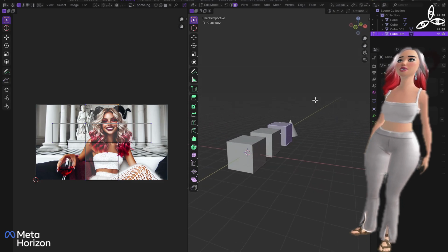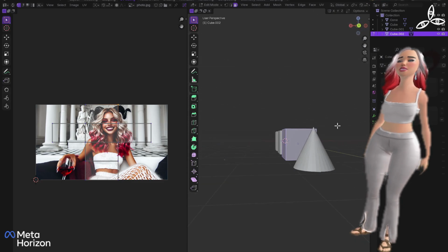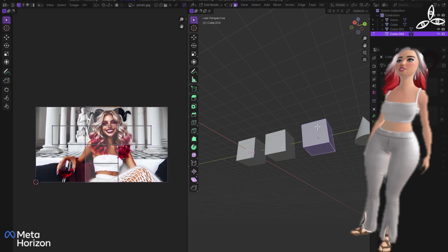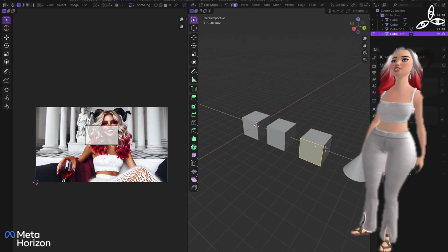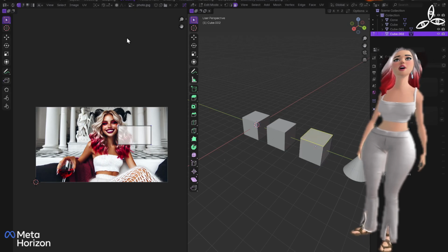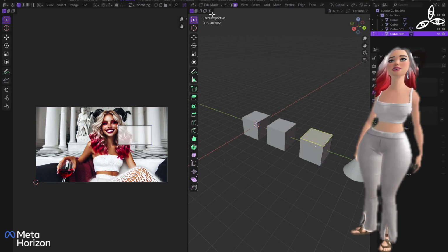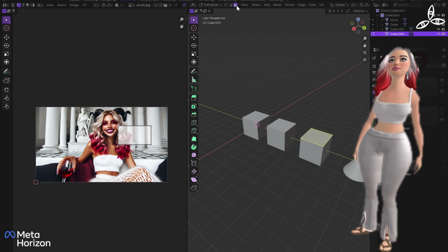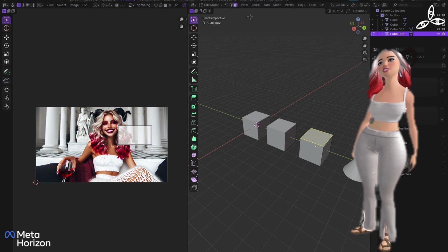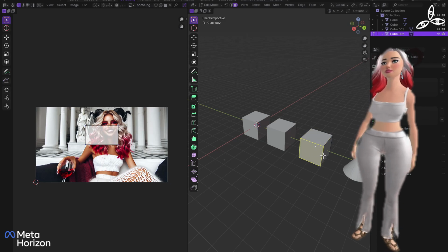But that said, you've got another 3D view over here, which again you can orbit just by holding down mouse wheel. That is a thing. So with this object selected here, you can actually see when I've gone in here, if it's not allowing you to choose faces, by the way, make sure you're on face select mode. So to do that, you have to be at the top here. Face select mode is just here, and if you're not able to select them, then of course you're not able to see that, and you just need to press tab with your mouse over this window.